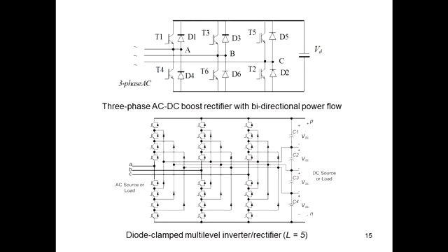We call this type of converter a 2-level converter because, depending on the DC voltage, the terminal voltages here, here, and here, the line-to-line voltages, can only be of two levels. Either VDC, if you switch this transistor on, this potential is VDC. If you switch this on, this potential is 0. Or if you divide it into half and half, it would be plus VDC over 2 and minus VDC over 2. So this is called a two-level converter.